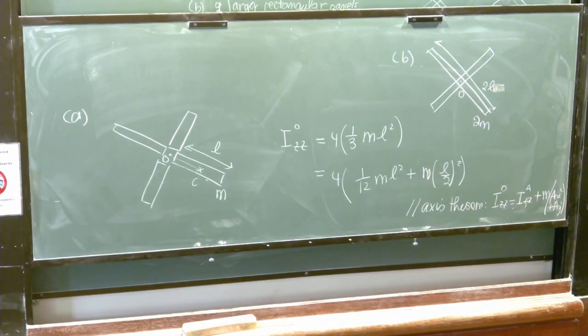I don't think it's a sphere, it's more of a cylinder. Yeah, it's more of a cylinder. But which equation are you using though? The angular momentum before and after has to be the same with a different moment of inertia. Why is angular momentum conserved? Because he can't exert any moments on himself. Right, there are no external moments being exerted on the body. Yeah, that's right.